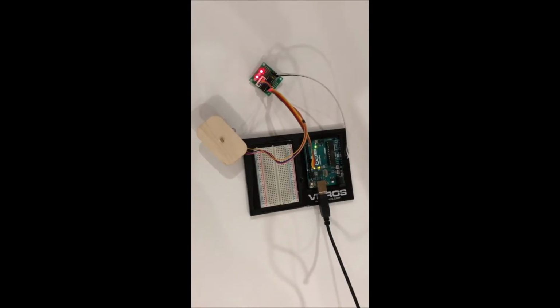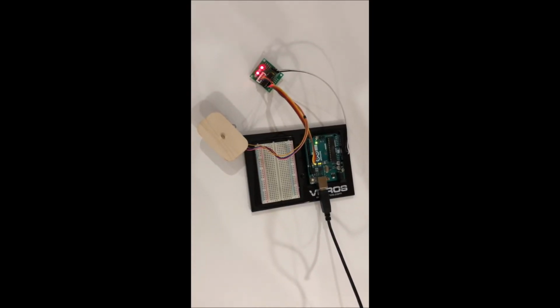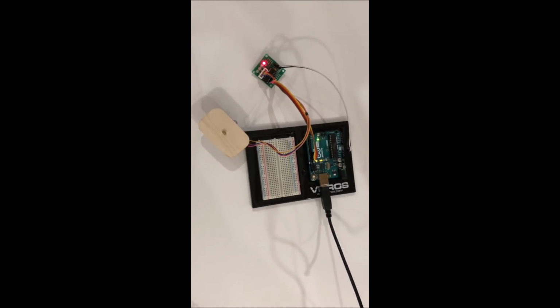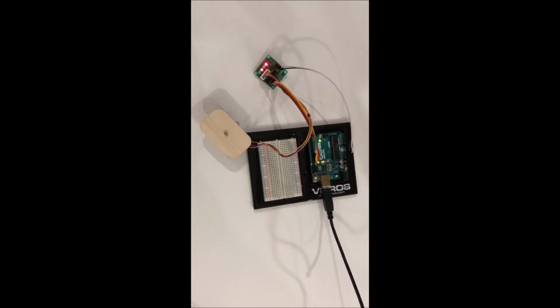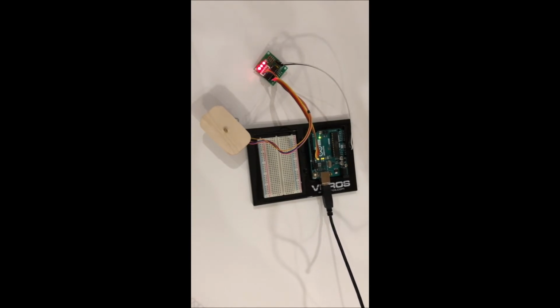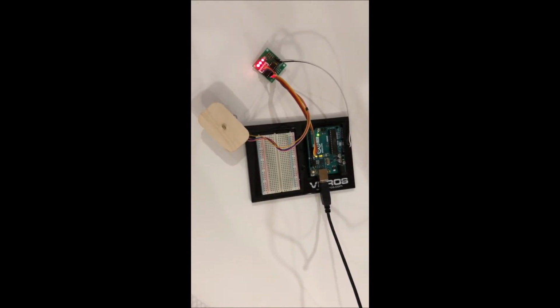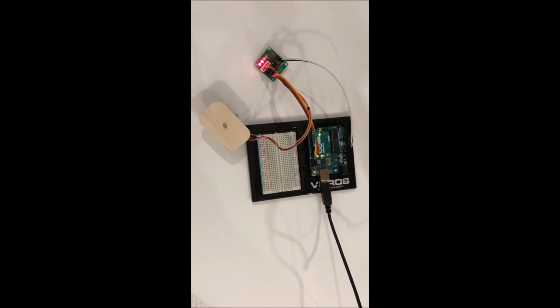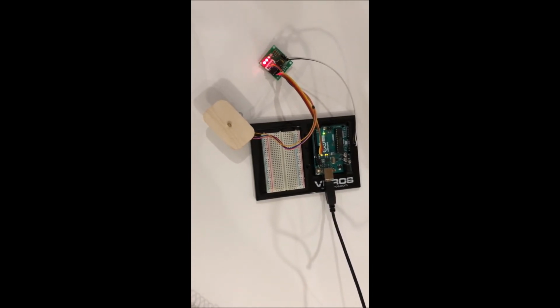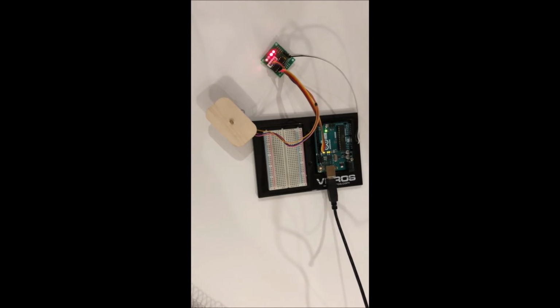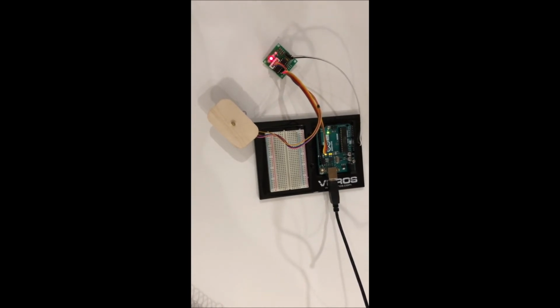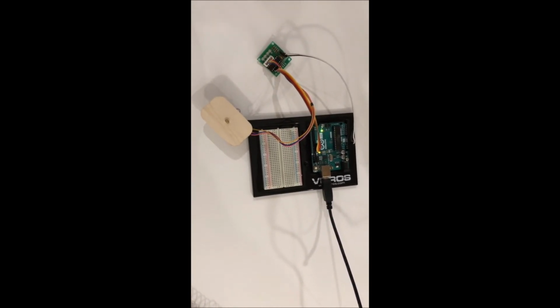My stepper motor isn't working. That's a problem, and I need to figure out what isn't working and fix it. Now, there's a lot of reasons a stepper motor might not work. The code might have errors. The Arduino might not be connected. The board that the Arduino is on may not be plugged in. It may be wired wrong. There could be a short somewhere on the board. The stepper motor could be broken. The wires could be bad. And maybe there's more things beyond that.